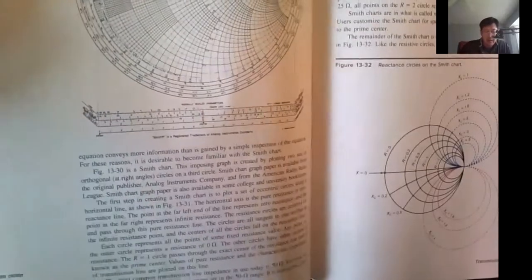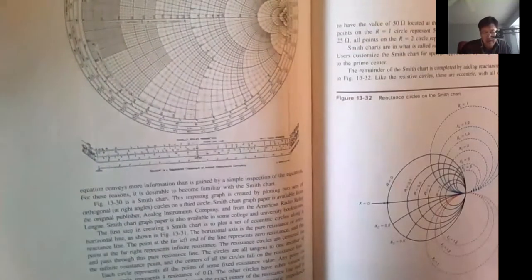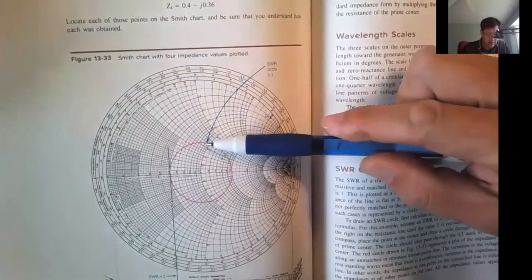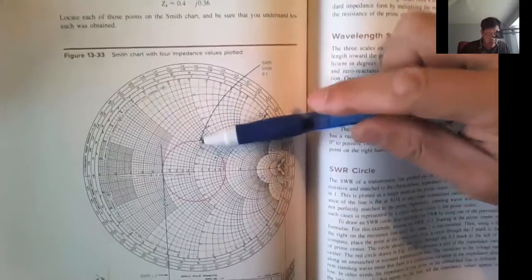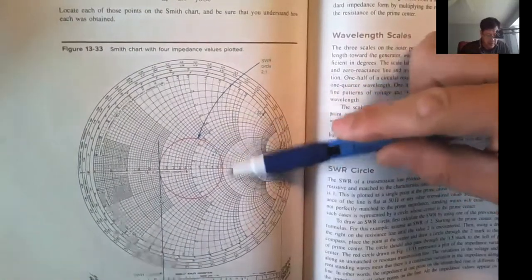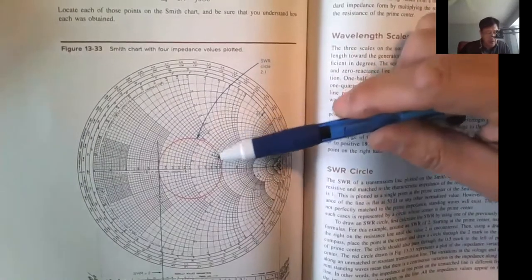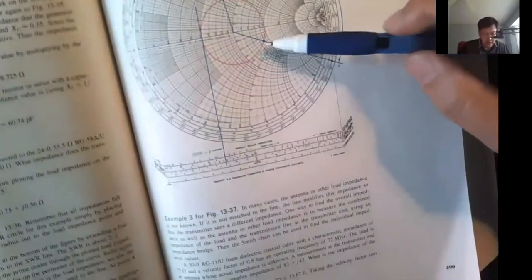The reason I did not go into the detail of the Smith chart is that the detail is easy to learn when you're really working in this field. Otherwise, it's very easy to forget. Anyway, all you need to know is you start with your load impedance, wherever it is located on this chart. And then you draw a red circle. That is the SWR equal to 2 circle. And then you just travel. So if the cable is 48 feet long, you need to travel twice the distance. So you start from here.